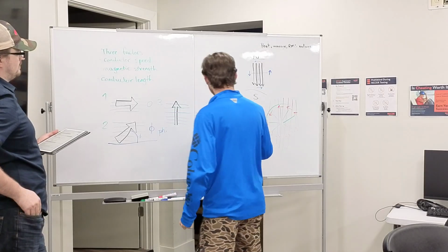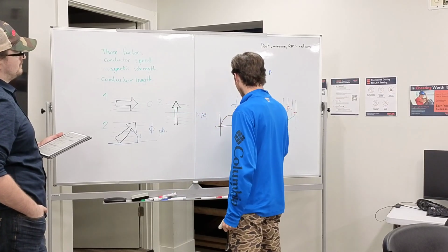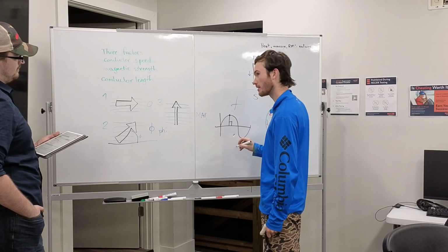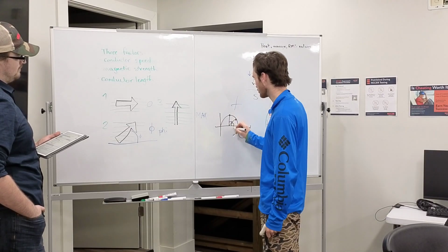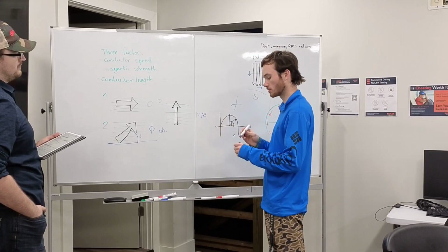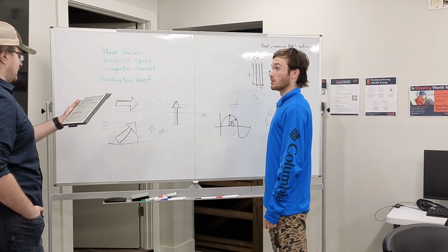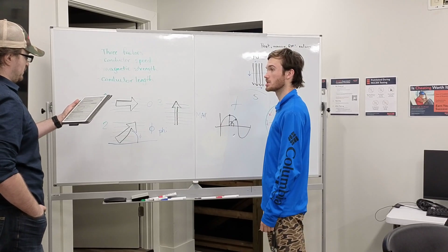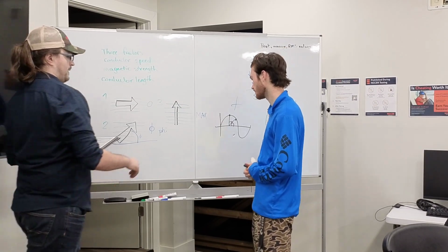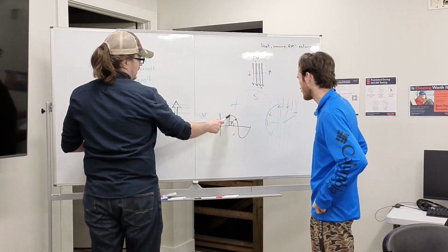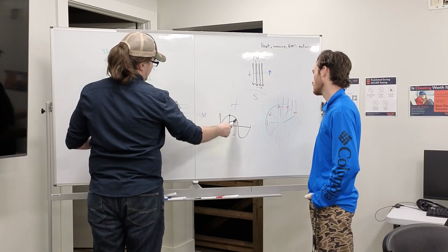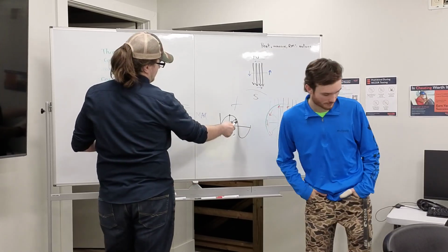It's going to be proportional to that. Proportional to what specifically? The time axis. The magnitude of the voltage produced by that interaction will be proportional to the sine of the angle of that interaction. Oh, the sine of that angle. Yeah. That means the voltage here is the sine of this angle. Sine of 90. The voltage here is the sine of whatever that angle is, and so on and so forth.